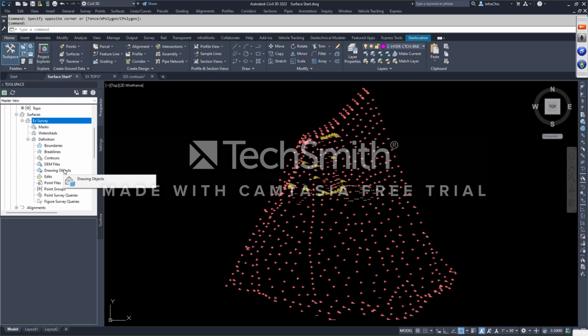Drawing objects. I'm going to expand this out a little bit more so you can see that. Multiple different things for drawing objects. Survey points from like Eagle Point, Carlton. They make these point objects that are points, but they're not Civil3D points. That's where they would go under drawing objects. There's also blocks. If you put a block in here and you elevate that block, you can use a block. Text, elevated text. MicroStation does this. When you get a file from MicroStation, the text is elevated if it's a survey object. You'll say 83.67, and it will read in its properties as a Z elevation of 83.67.